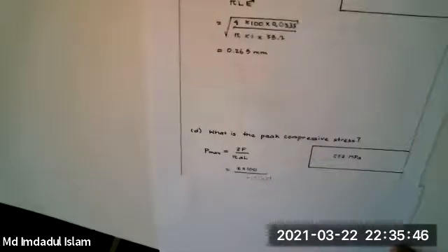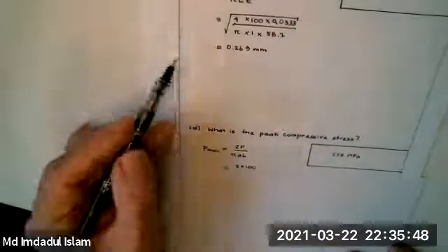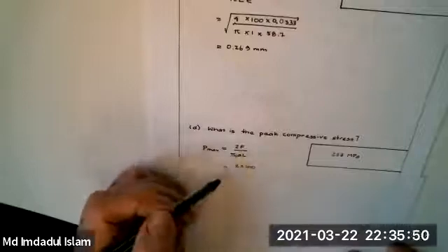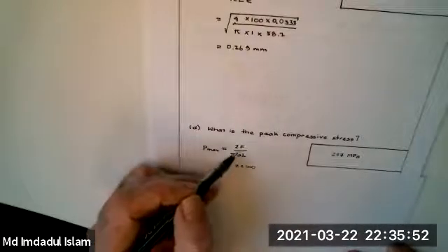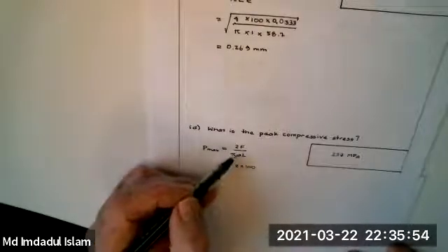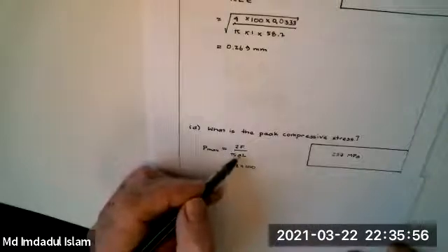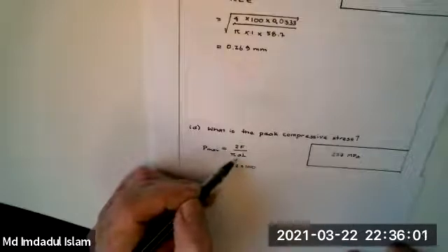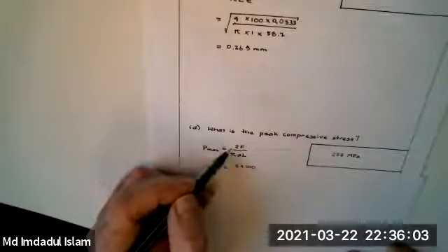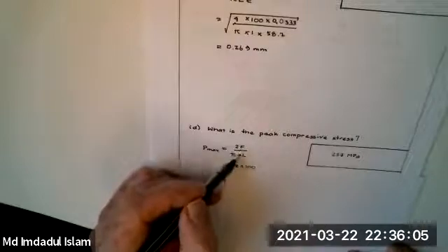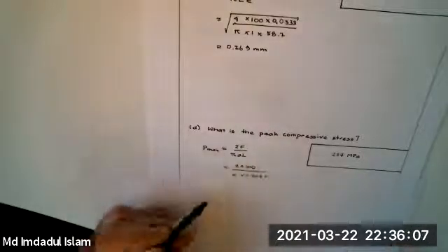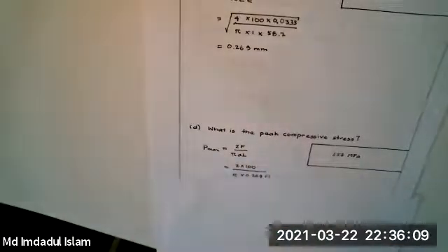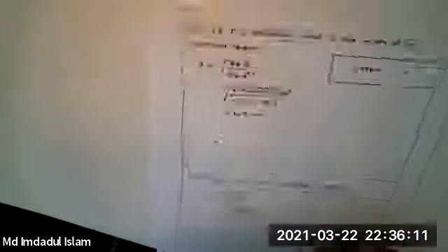And the easiest formula to use to get the peak compressive stress after you compute a is this, although there is another formula which you could use. Okay. I didn't write that down, but it's 4 upon pi times the average. Okay, the average would be F upon 2aL. Some of you remember it that way, which is fine. 4 upon pi, F upon 2aL is the same as this formula. And you substitute the numbers and you get 237 megapascals.